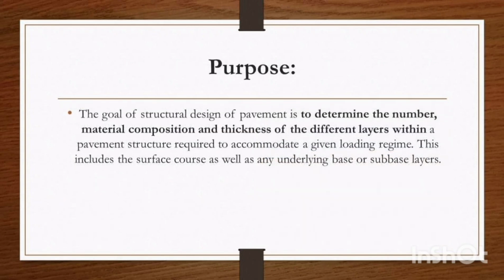The goal of structural design of pavement is to determine the number, material composition, and thickness of the different layers within a pavement structure required to accommodate a given loading regime. This includes the surface course as well as any underlying base or sub-base layers.